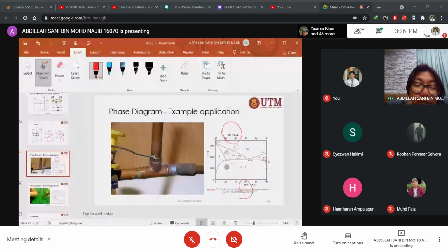It is helpful for us to understand, in this case, alpha and beta, the ratio, and the properties of alpha. If we shift a little bit and make more beta, what happens to the solder? Okay, so that is the application of the phase diagram to understand the behavior of the material when we combine two metals.